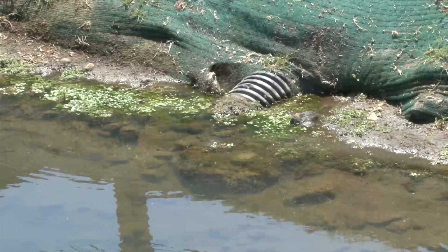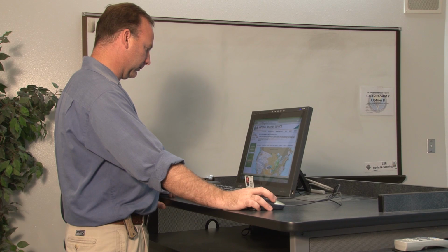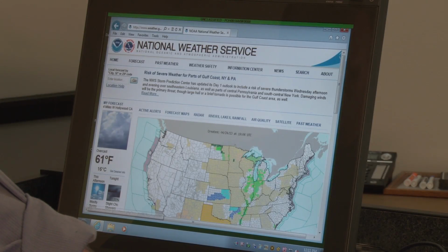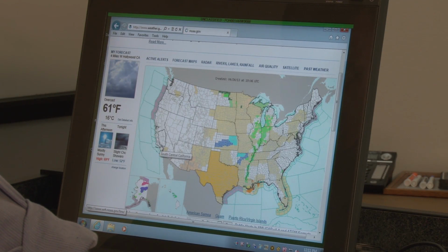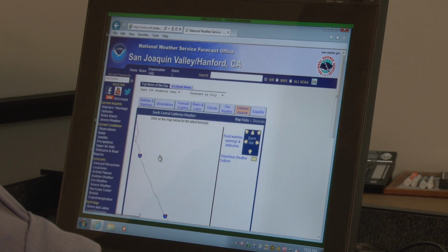As a pre-sampling activity, check rainfall data daily. This activity is necessary because the EPA requires that a period of at least 72 hours transpire without precipitation of 0.1 inch or greater prior to the sampled event. There are different methods to check rainfall. You can use a traditional rain gauge or use technology to check rainfall data through websites such as NOAA.gov, which is sponsored by the National Oceanic and Atmospheric Administration.